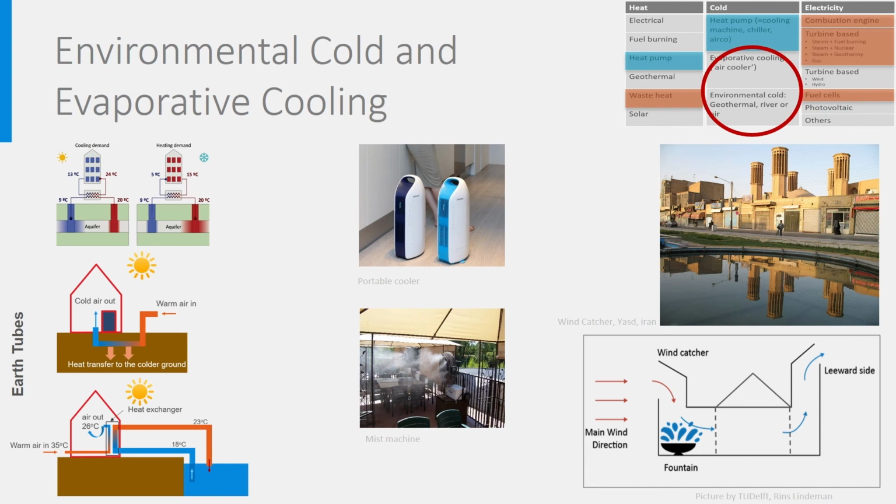dry air. Evaporative cooling is very efficient in terms of energy usage, and we can by approximation neglect the energy use of the pump, by which primary energy and CO2 emissions are 0. However, it is not applicable in humid countries, as the air there is already close to saturation.